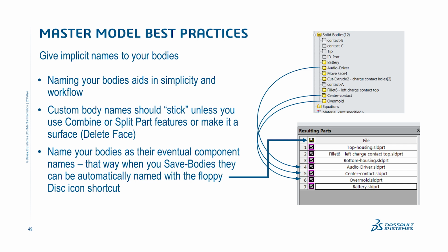Another important thing to do, and this goes to the organization, is to name your bodies in your master so that they can be easily isolated and looked at by anybody coming into your master file, and they can be understood. So usually they are named per the quasi-component they're going to represent as a derive.